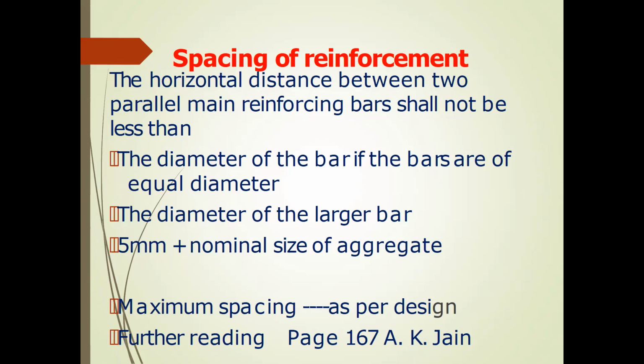If it is 20 mm metal, you should have a minimum of 25 mm. Maximum spacing is as per design. You can refer to the A.K. Jain book also.